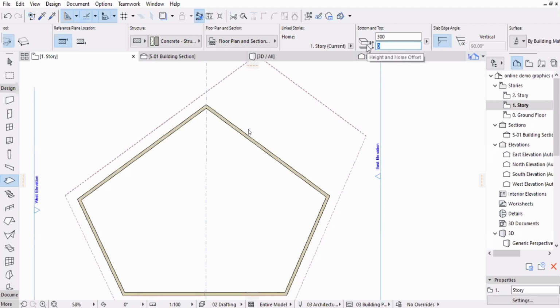The wall height is always taken from the bottom. For any other tools, whether you do a roof or whatever, it always takes the bottom generally. But only in the case of a slab, the height is taken from the top of the slab and the thickness goes down, right? And don't worry, this is not zero, it's not ground. Actually, it's because you need to see the actual height we are drawing the roof and the slab at, because we're on the first story, is not zero.